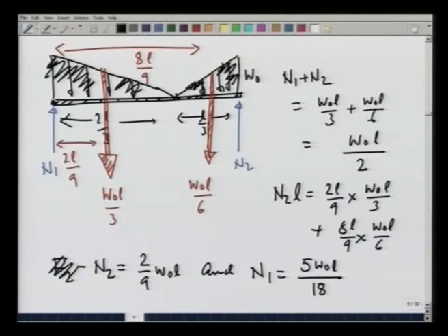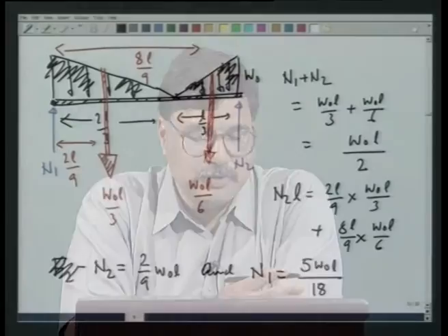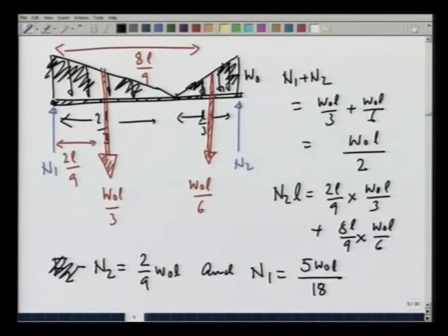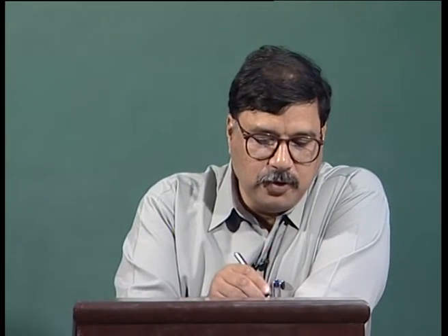So, that is how we have used the concept of centroid in finding out where effectively the force given by a distribution acts, what is its moment, and then applying regular point force diagrams to calculate the reaction forces and so on.